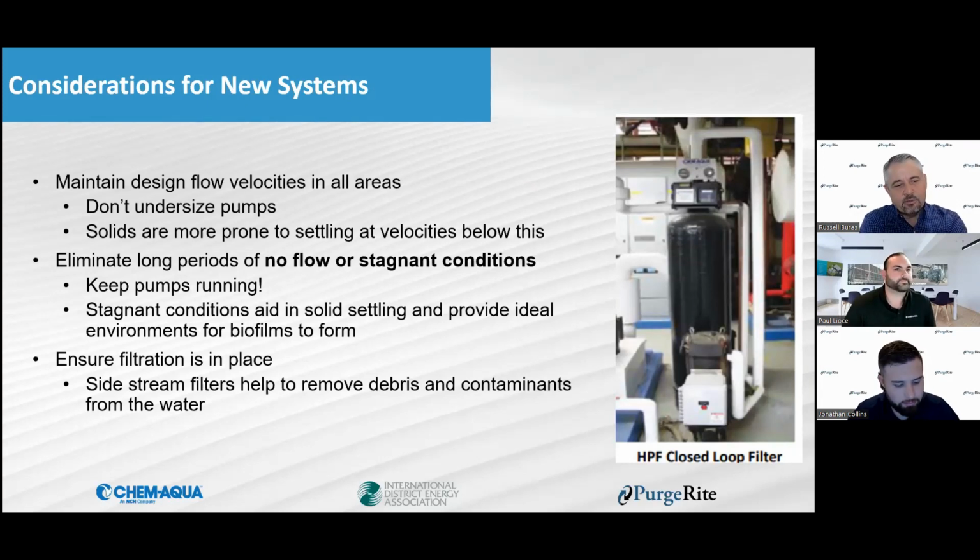Yeah, what we want to talk a little bit about is your new system. Just a couple of considerations: from an engineering design standpoint, make sure you don't undersize the pumps, and you have to have velocity to move systems. This goes into people turning systems off at parts of the year and different things like that. These are things that all need to be considered when you're trying to maintain the system.